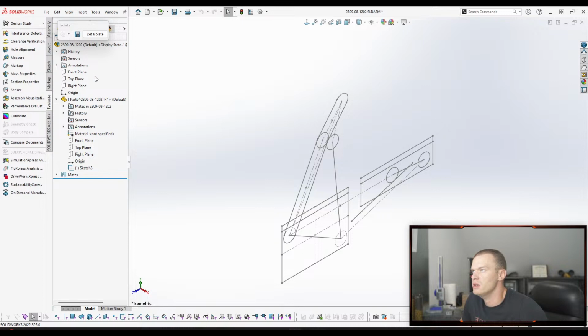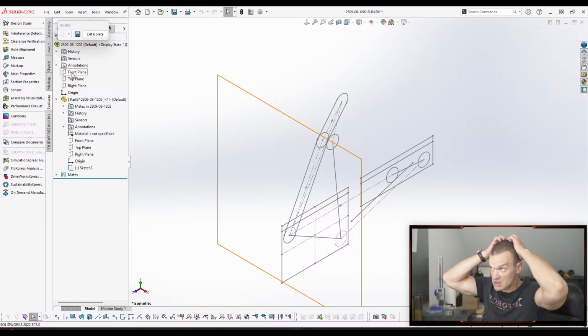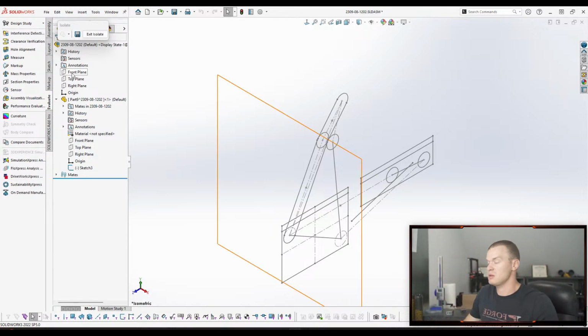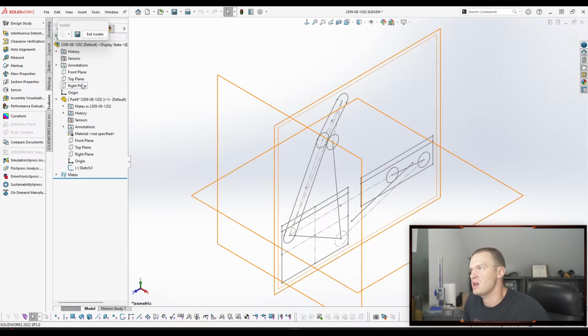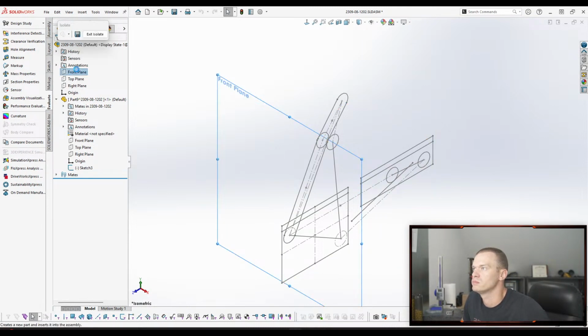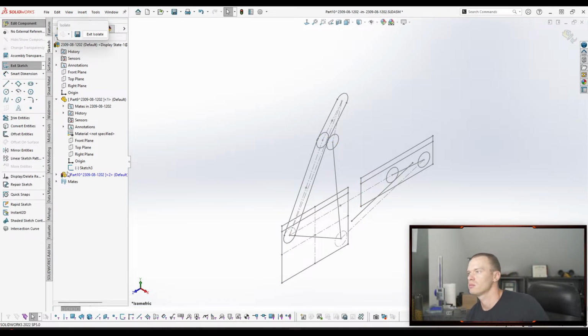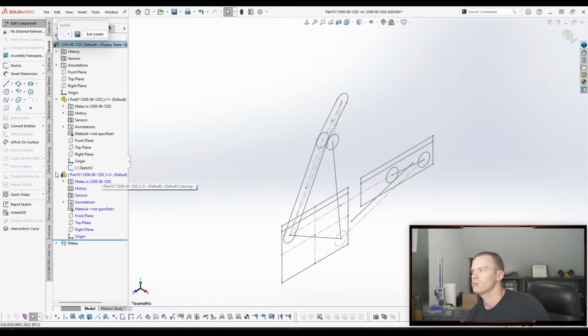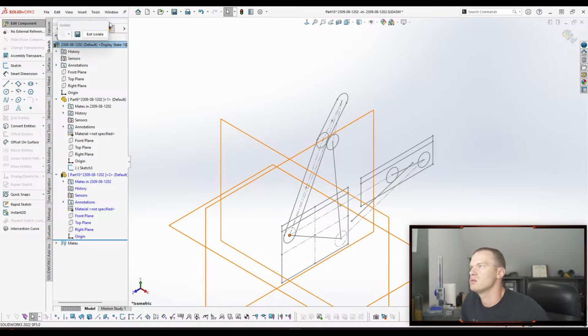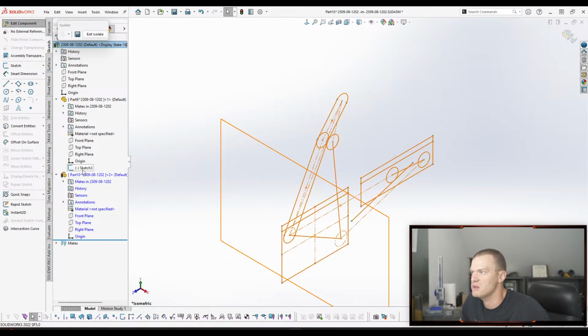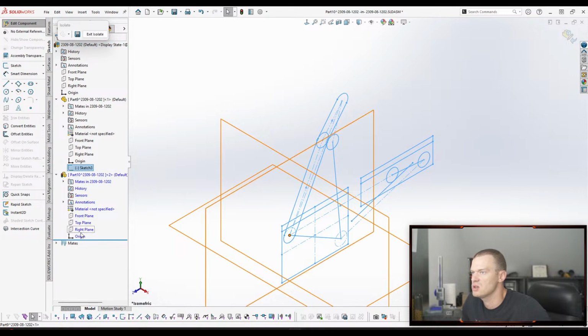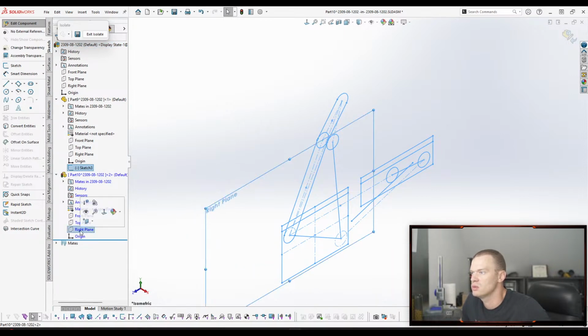So we'll get out of here and we'll redo what we did. Like we deleted parts at the beginning of the string, and we're just going to recreate those parts, but create the correct geometry. So we're doing the skeleton sketch technique, which means that we're going to derive these sketches into the part.